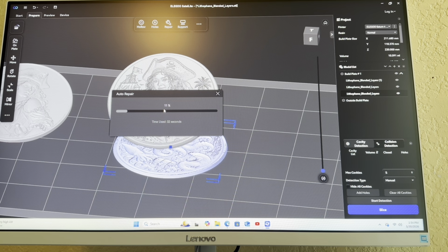So I have some corruption issues. I had to create or change the photo, pretty much make an STL file, and then transfer it to this system. But every time I transfer it to here, it's showing corrupt. Therefore, I have to fix it. And there's a repair option, which it did one time already. I'm gonna see how this works.